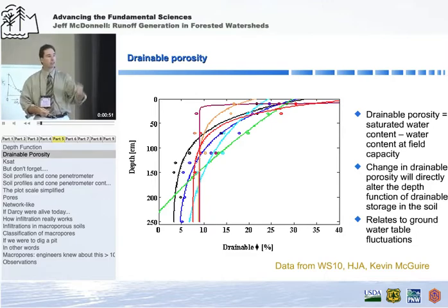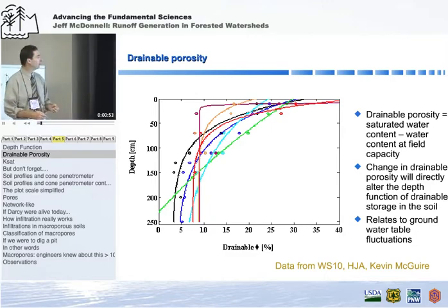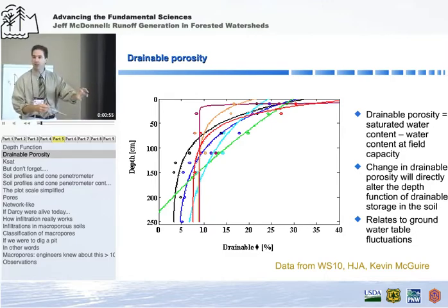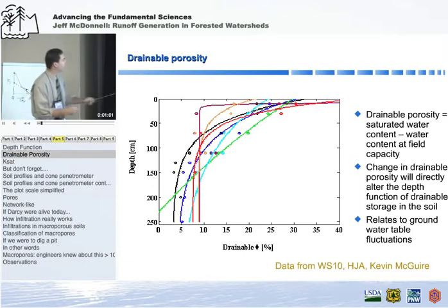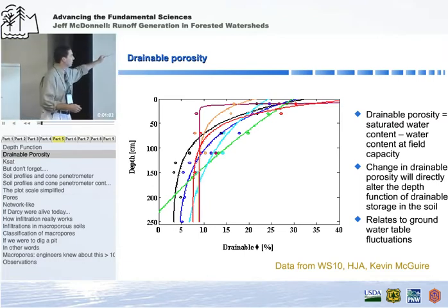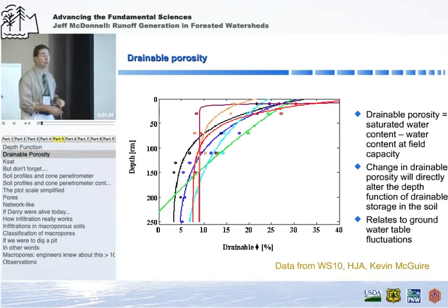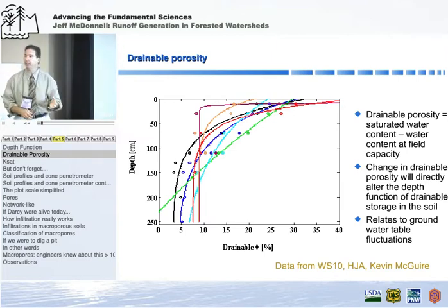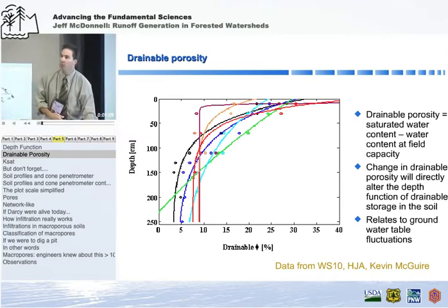So you're working at a site in the Tongass National Forest. You can go out, take cores down through the soil profile, compute the moisture release curve for those soil cores, and then that is going to give you bulk density at those different points where you've extracted the cores and allow you to define that depth decline in drainable porosity.